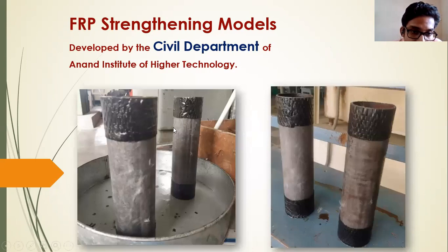This was just after applying the FRP. These are the carbon fibers you can see here that we have used for this project. These are 30 centimeter samples only, just to see the behavior of the fibers and how they work. Different types of fibers behave in different ways in load carrying capacity. These are unidirectional fibers, and we have used them with the orientation of the fibers towards the direction of the application of load.